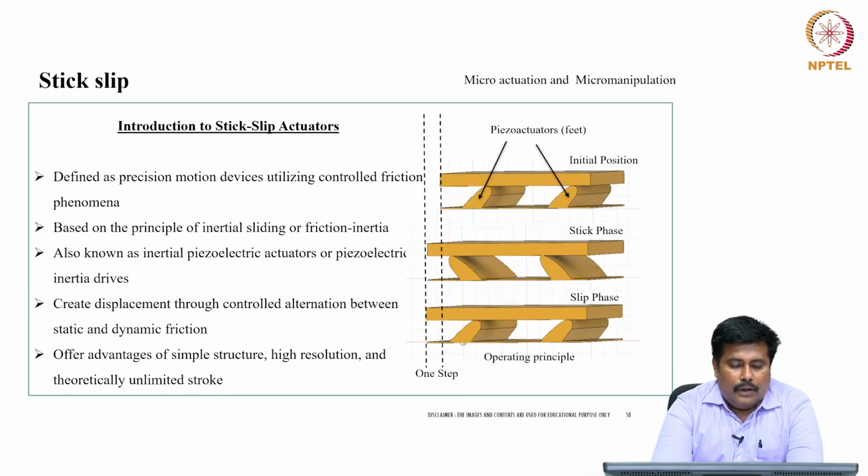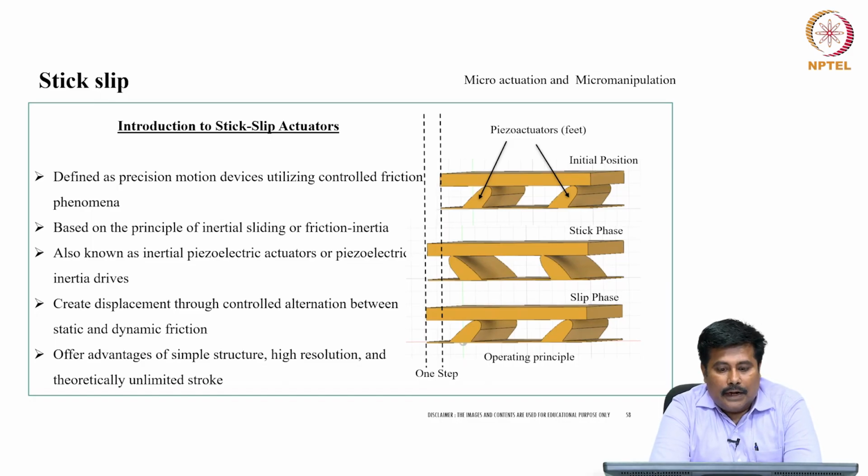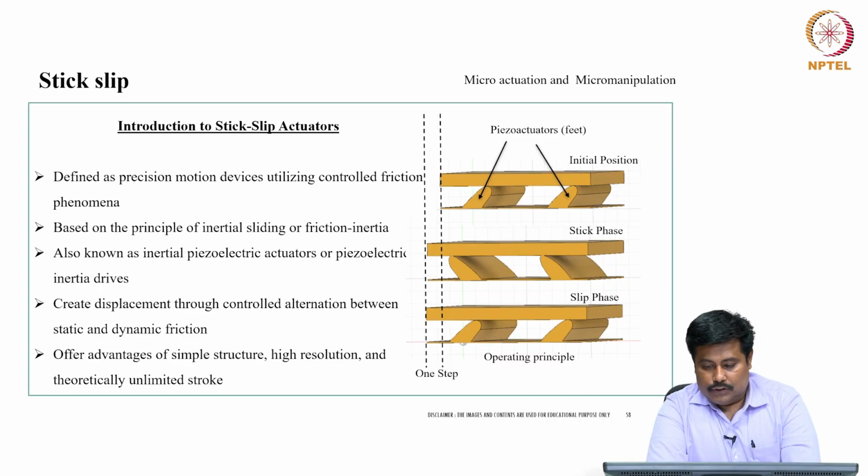stick slip actuator. These stick slip actuators are defined as precision motion devices utilizing the controlled friction phenomenon based on the principle of inertial sliding or friction inertia. They are also known as inertial piezoelectric actuators or piezoelectric inertial drives. It creates a displacement through a controlled alternation between static and dynamic friction, and it offers the advantages of simple structures, higher resolution and theoretically unlimited strokes.